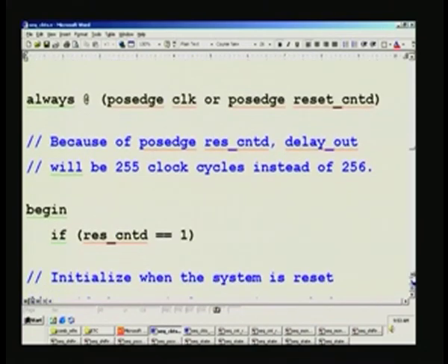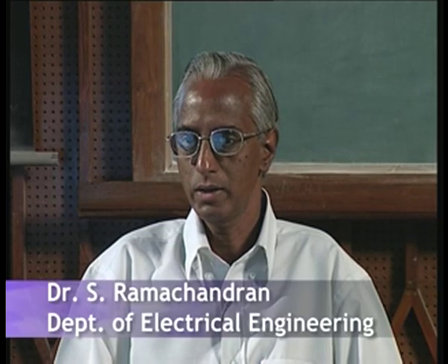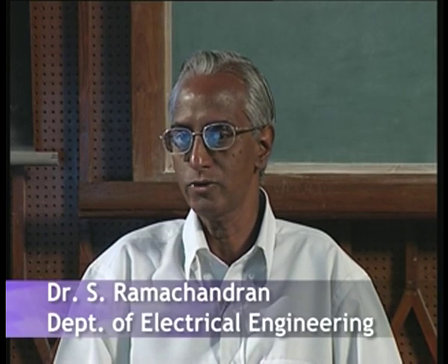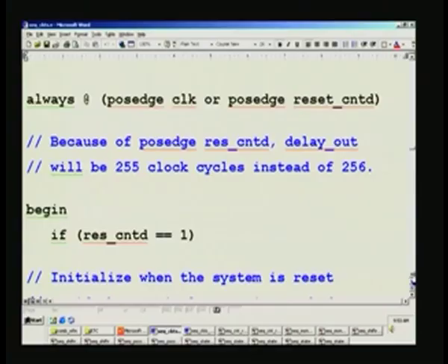Yes. This is a standard way to sense the change in clock, like rising edge or falling edge? No, not necessarily. You can put a flip flop and realize straight away, so as a clock input, but another rule we will be violating. All the flip flops etc. should have a system clock alone fed to that. So naturally that is not a correct way of RTL coding, right. So the best thing is to realize in this fashion.